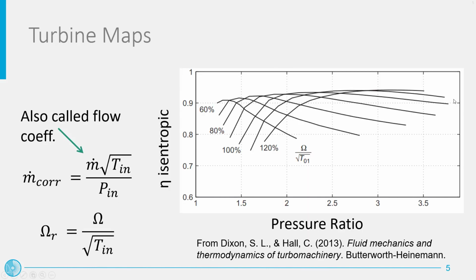A 2D map can be defined also for the isentropic efficiency of turbines. In the slide, you can see the trend of isentropic efficiency versus expansion ratio and reduced speed. From this chart, you can notice that turbines can be optimized at part load by changing the rotational speed. In theory, the performance of the machine can be kept very close to that of the design point over a wide range of expansion ratio values. Unfortunately, the rotational speed can be generally actively regulated only in small capacity turbines.